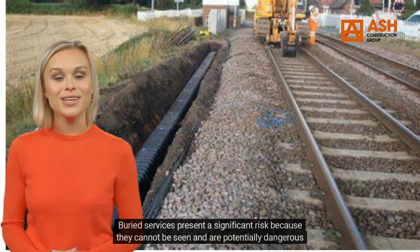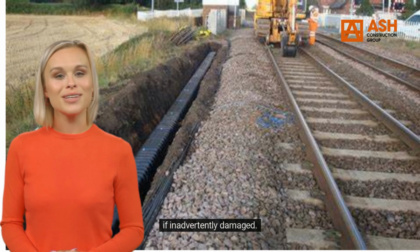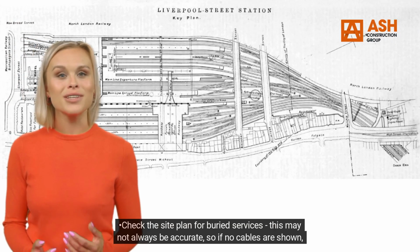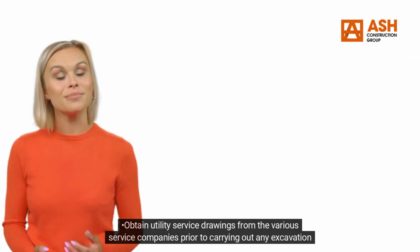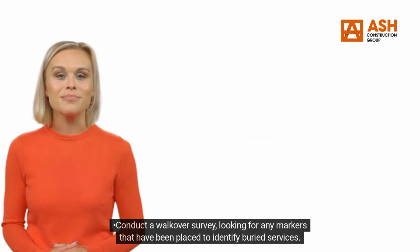Buried services present a significant risk because they cannot be seen and are potentially dangerous if inadvertently damaged. Before any excavation work starts, you must check the site plan for buried services. This may not always be accurate, so if no cables are shown, don't assume that none are there. Obtain utility service drawings from the various service companies prior to carrying out any excavation work.